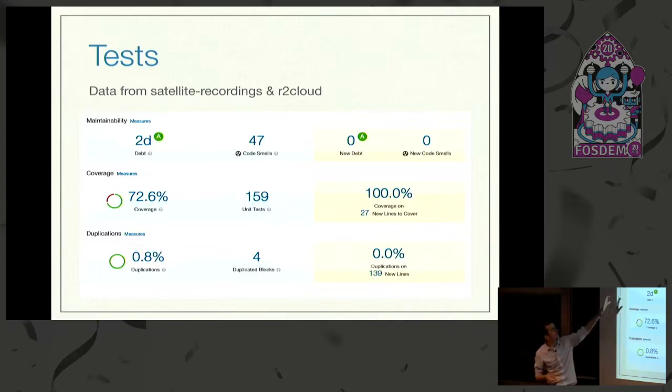So what's the difference between the two? Satellite recordings contain a very strong signal, which is very useful when you want to test your decoders. You want to make sure that you understand the protocol properly, and it's easier to do reverse engineering. But if you want to decode a signal in the wild, you have to deal with multipath, with Doppler, with a neighborhood antenna, and whatever might come up.